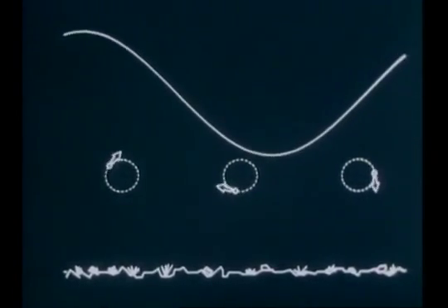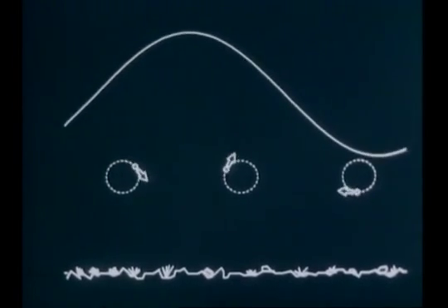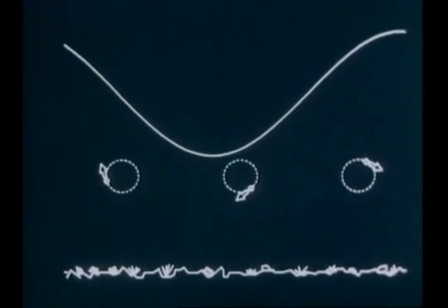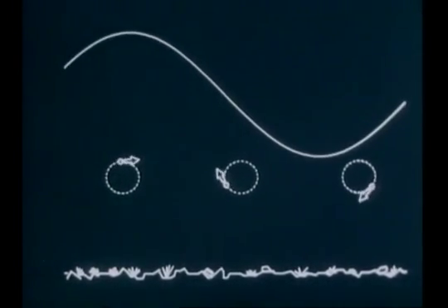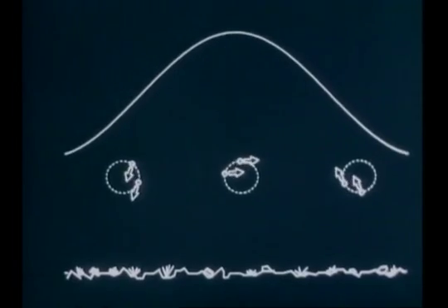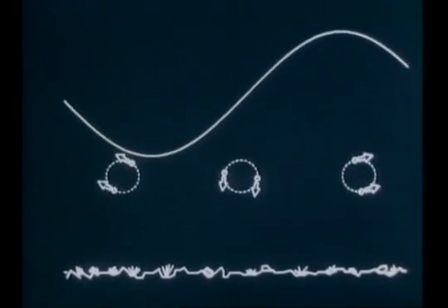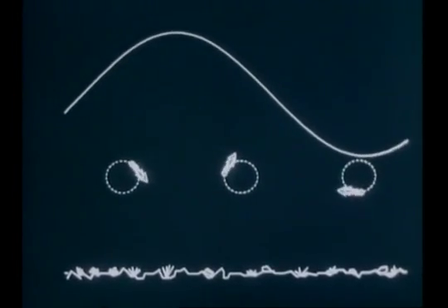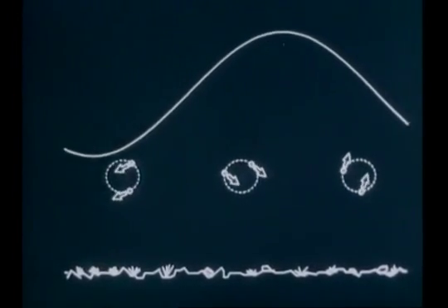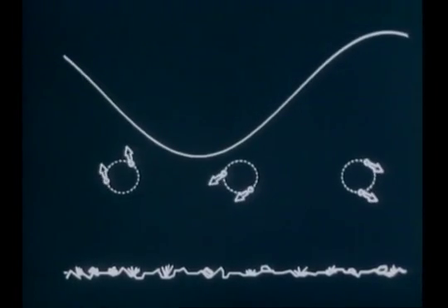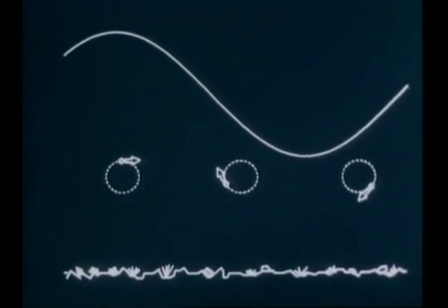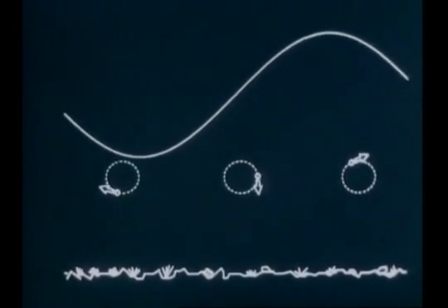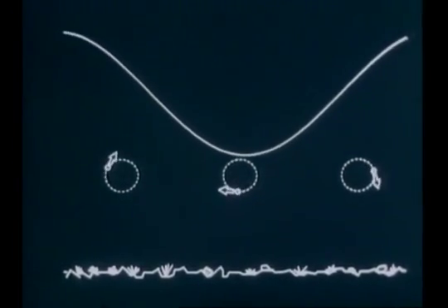Here are the velocities of the moving points, the Lagrangian velocities attached to the points, and here also attached to their initial locations. In any flow, the Lagrangian field can only be steady if each material point always experiences the same velocity. This degenerate case only happens in a steady parallel flow.